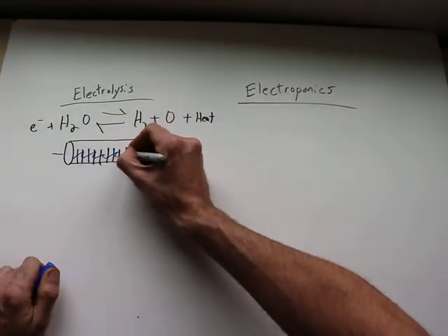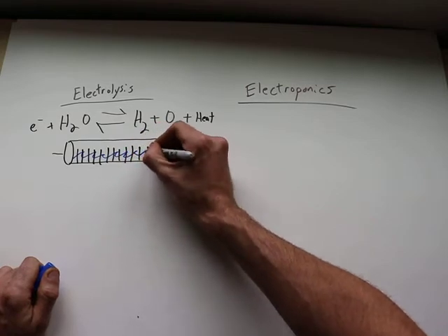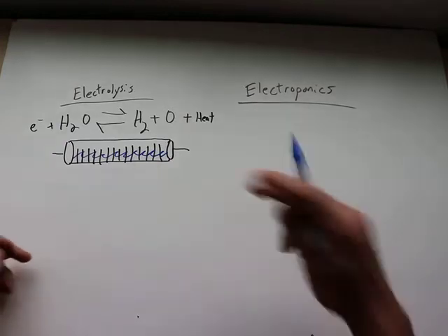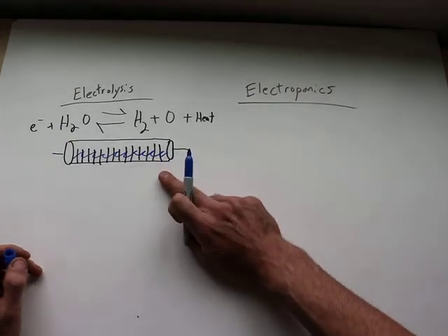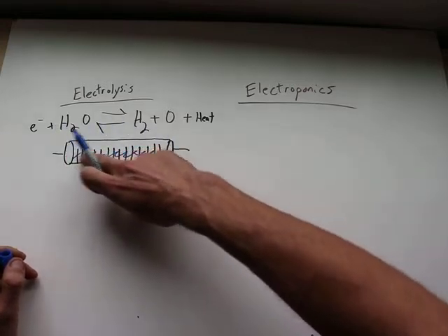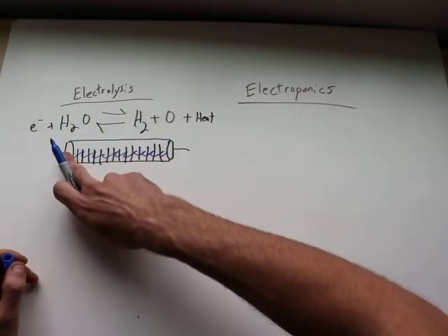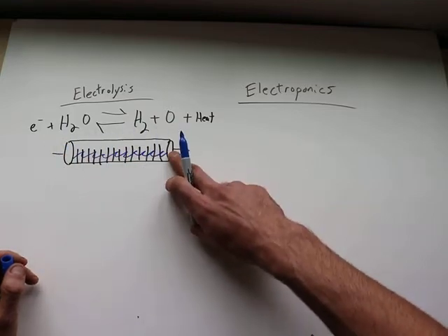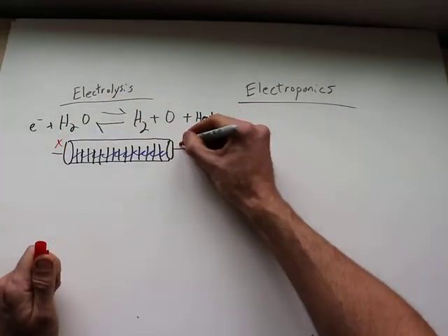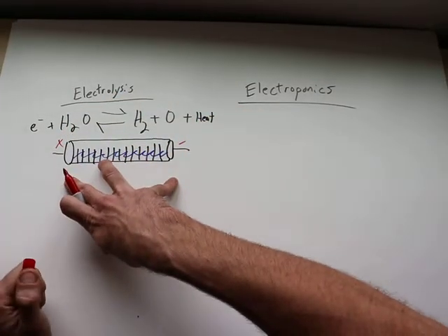Within the plates there's electrolyte, or the water that we want to create electrolysis with. There's also caustic soda, NaOH. We're using that salt in order to increase the conductivity and reduce the resistance of this liquid, in order to facilitate the flow of amperage across here when we apply a voltage on either end of the electrolyzer.